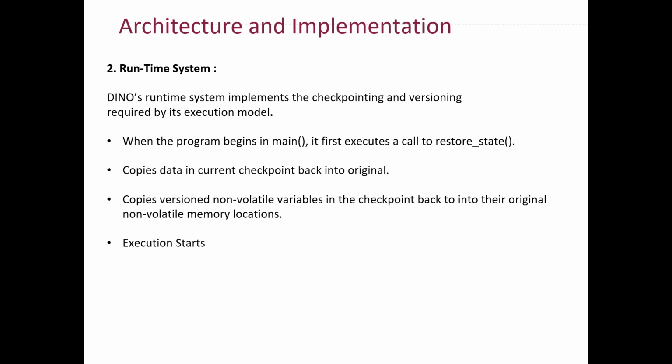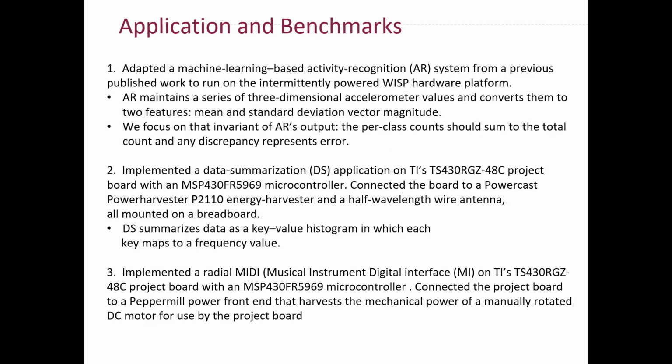So restore state just takes all the data from your wallet. It halts the program, takes data from your volatile memory, and stores it exactly at those places where it needs to be for the program to run as if it's continuous execution. And once all of that is done, it moves the instruction pointer, stack pointer, and frame pointer back to your main function, and your main function executes until it hits another DINO task. So this was the whole execution of DINO.